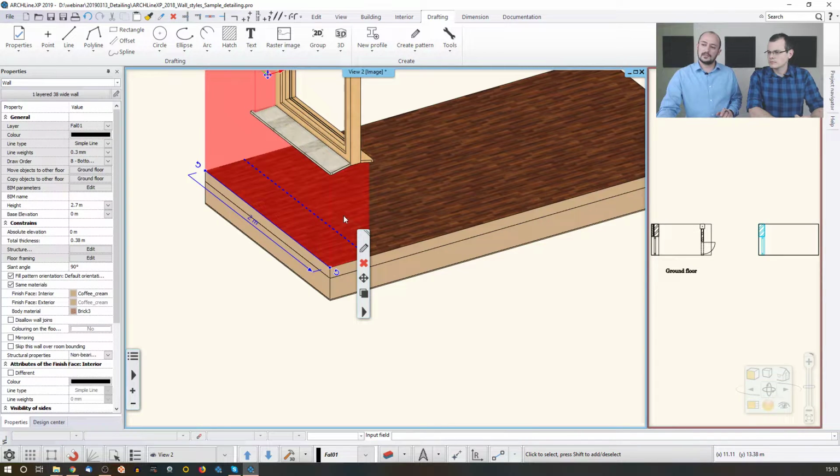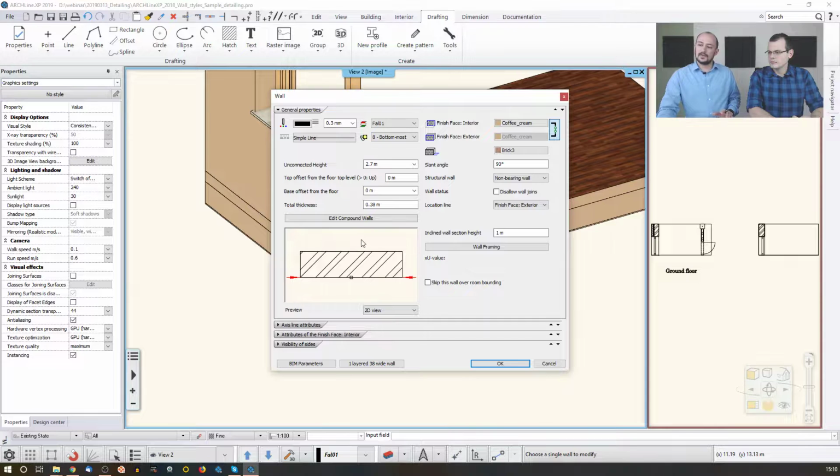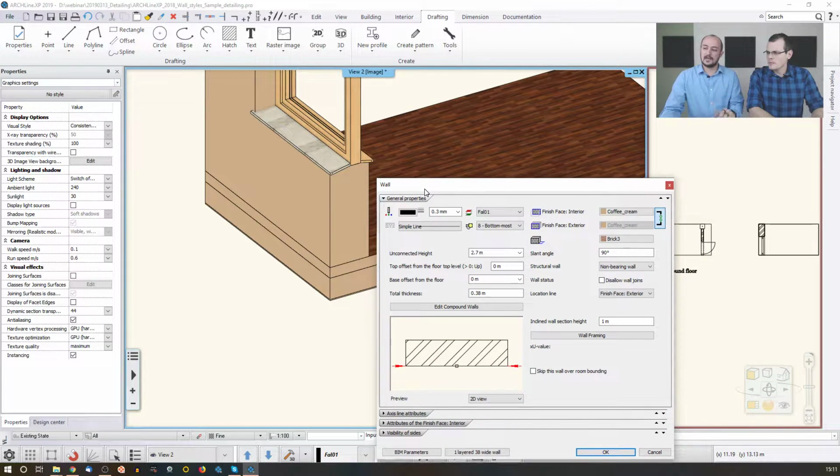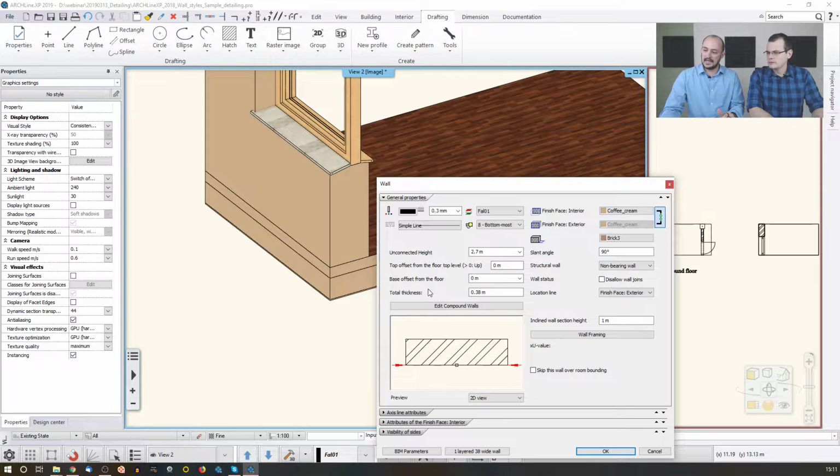So I just go to the settings of this wall as well, and let's just figure out what should I do. First things first, this wall should not start at the top of this floor surface. It should start from the top of the structure, top of the core structure. So I should change this elevation. Now I can measure this and use that value here. Yes, or you could offset and push it downwards, or that's fine.